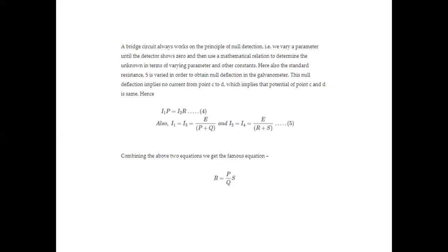Null deflection means no current flows from point C to D, which implies that the potential of points C and D is the same, Vc equals Vd.